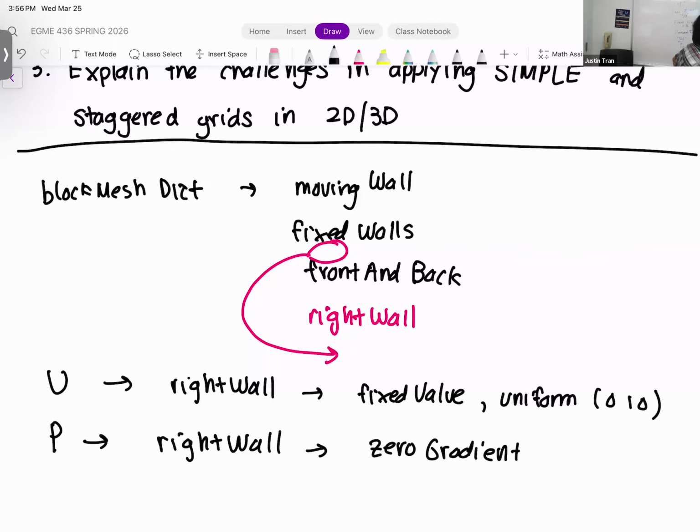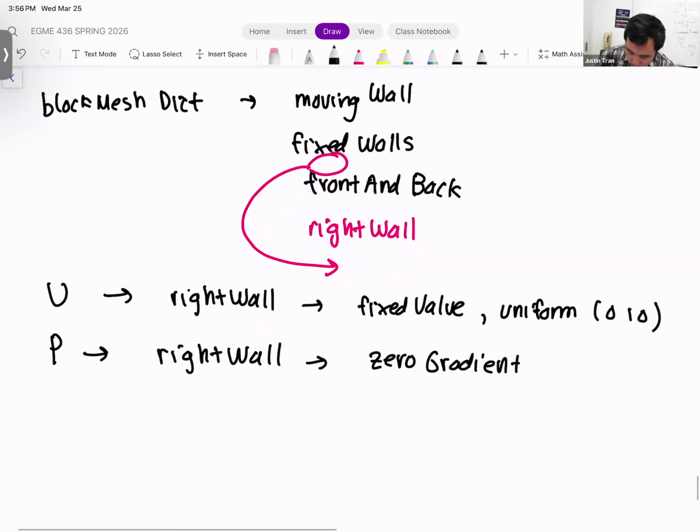Oh, interesting. Okay, so I think probably what you guys have to do is, I wasn't planning on doing this until the second activity, but I think you're right that OpenFOAM does expect you to define the condition for every turbulence variable as well. So what you can do is actually change the simulation type. If you go under momentumTransport.